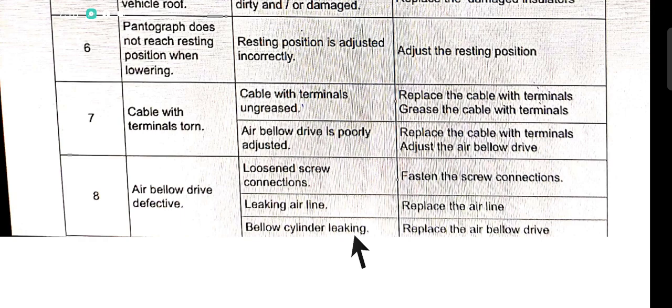If screws are loose, then we can tighten them with the help of equipment. But if there is any major leakage, or even any minor leakage, seen in the air bellow drive, then we need to replace that air bellow drive, because it is completely undesirable.